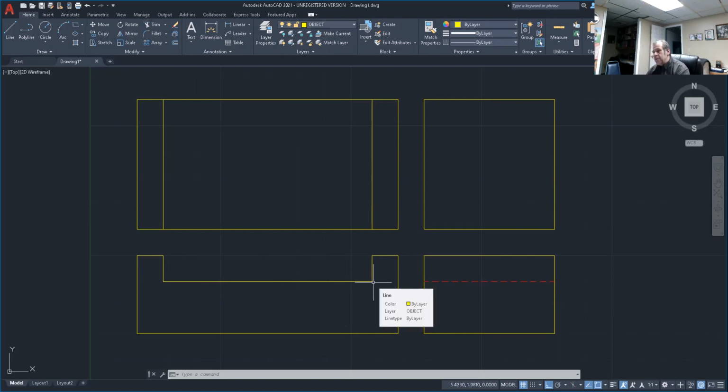And if you learn this when you get into 3D modeling and other things, it will make life so much easier for you. So the notch that goes in the bottom of this is going to be shown true size and shape in our right side view. Does that make sense to you? So we're going to draw this in our right side view, which means that we'll be dimensioning that feature in our right side view. If you look at the drawing, it's a 1/2 inch over, a 1/2 inch up, and a 1/2 inch over this way.